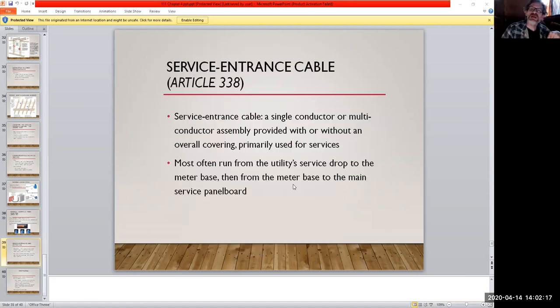Kind of cool. And I have an exercise where we'll go through and do a couple of calculations. We're on service entrance. So how do you calculate what your service entrance, or what your utility drop, is supposed to be? Let's say you had a 100. You still will see 60 amp services out there, you just won't see any new 60 amp services. I think a 100 amp is the minimum, and even that is starting to phase out nowadays.